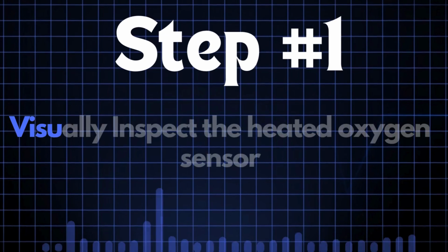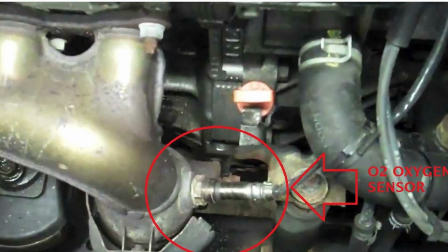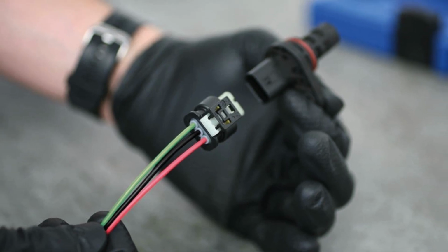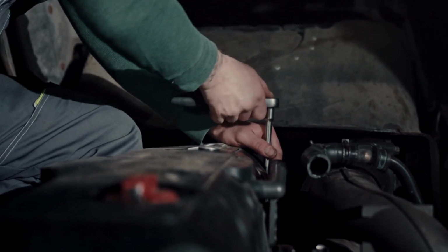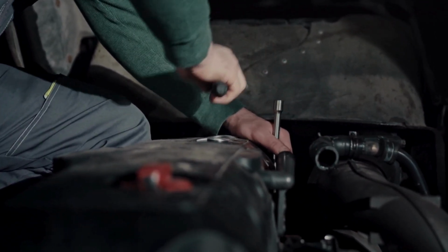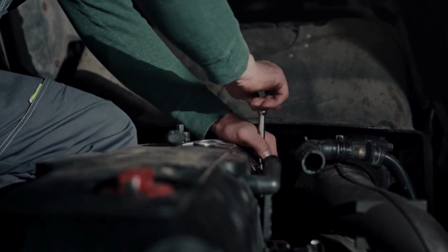Step 1. Start by visually inspecting the heated oxygen sensor. Carefully examine the sensor itself, along with the wiring and connectors. Look for any signs of physical damage, such as cracks, frayed wires, or loose connections. If the HO2 sensor appears to be damaged, it's best to replace it. Make sure to get the correct sensor for your car's make and model.